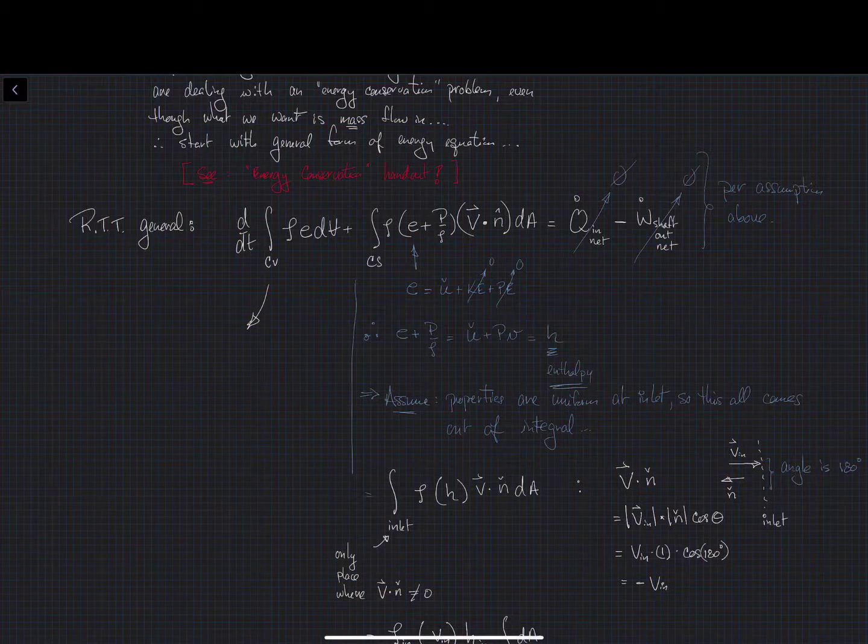Now I'm working on the transient term. And the transient term, let's start to play with the integral here again. I've replaced the thermal energy inside the tank by Cv times T, which is what it is for a perfect gas.